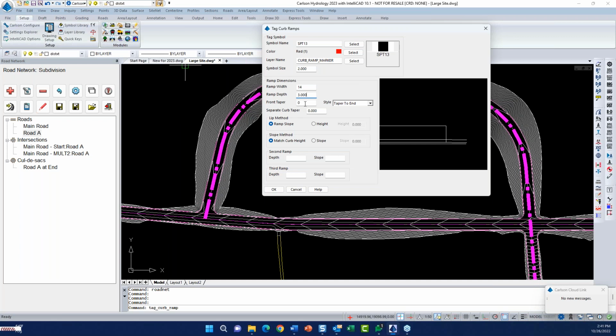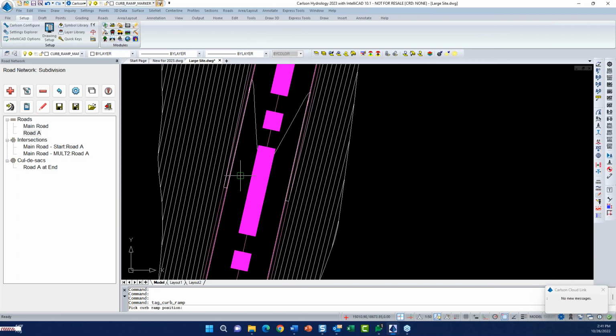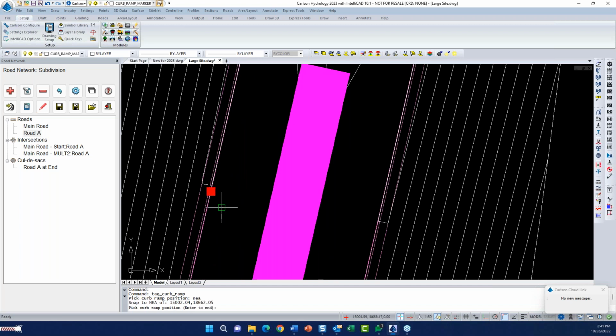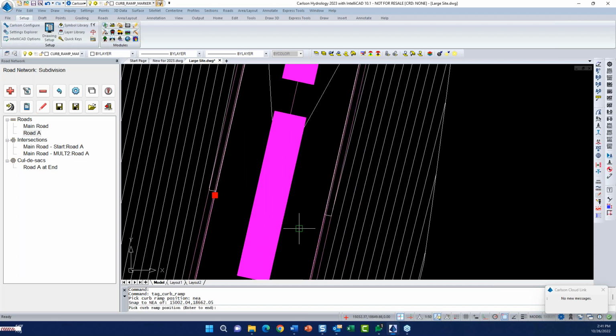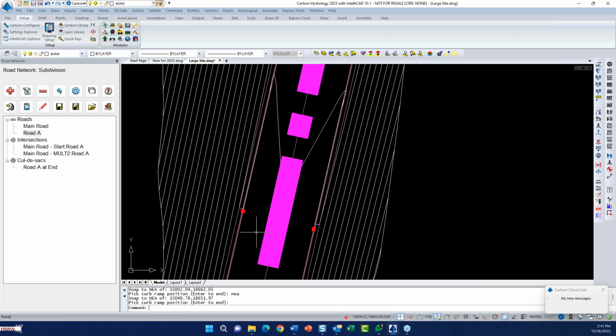I've got a curb template installed here, and when I hit OK, if I was going to have a driveway here, I can just go to this front curb line and hit nearest. I'm just snapping to. So there's going to be a driveway there, and I'll just put in those two to start with.